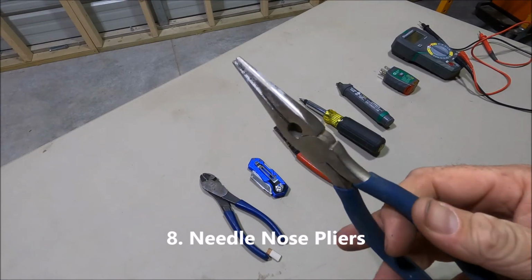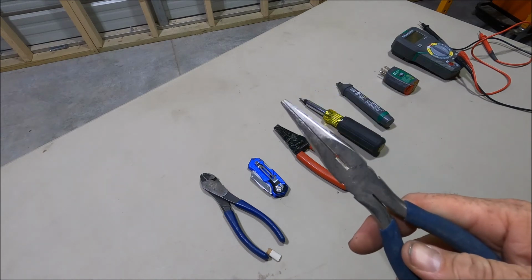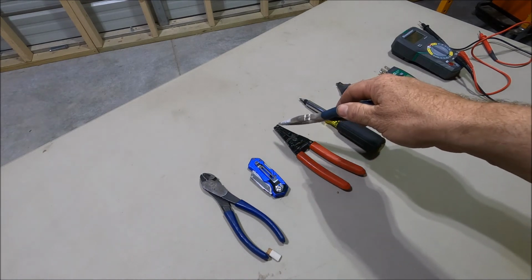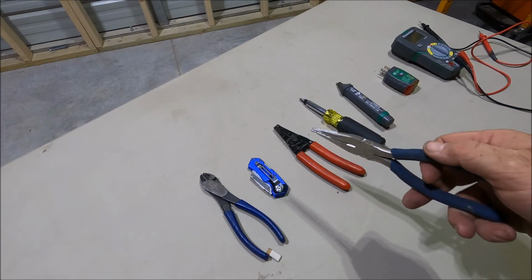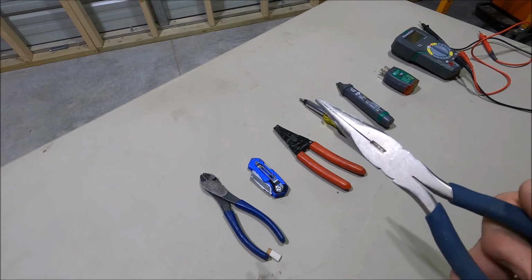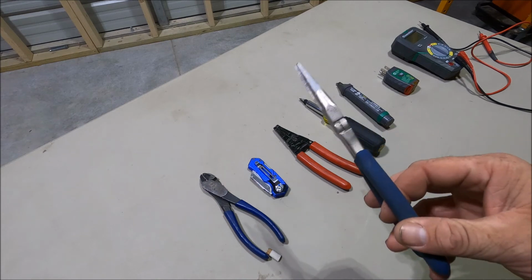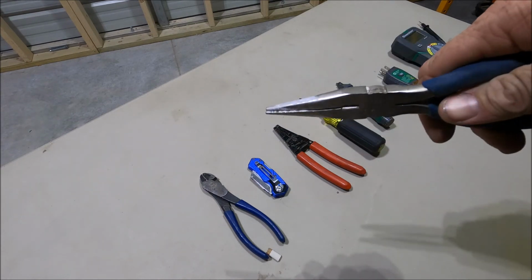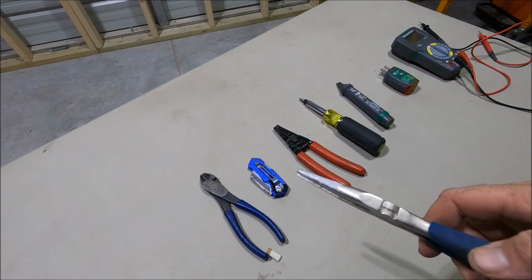I'd also recommend needle nose pliers. I use these a lot, and what I usually use these for, you saw me kind of curl the wire around the screws on an outlet with these, but a lot of times I'll use these instead. I guess I'm just kind of pressed for time and thinking about too many things when I'm doing videos, but I like using these and then going and using the needle nose to actually crimp the wire around the screw before I screw it down.